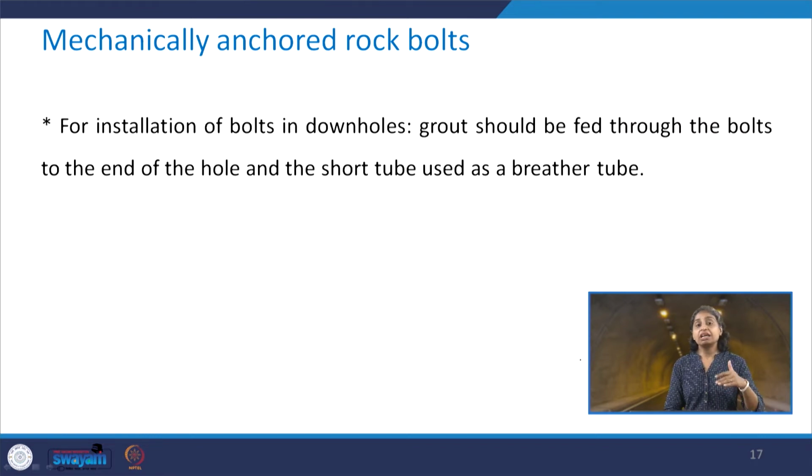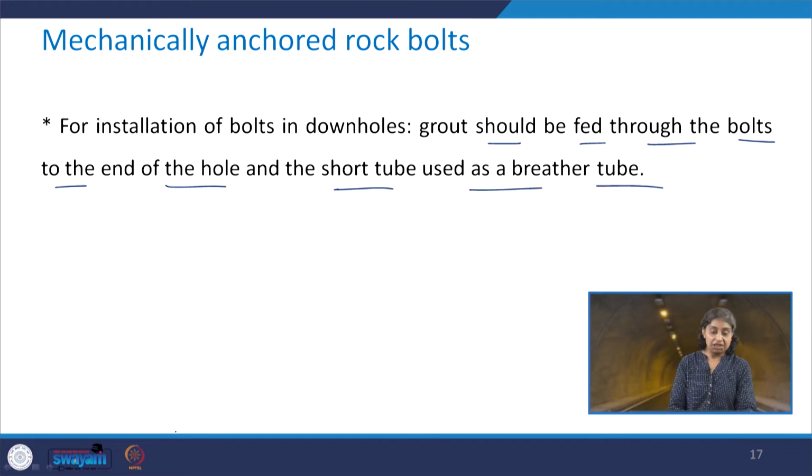Now, for the installation of bolts in down holes, so till now we were talking about up holes. If it is down holes, then the grout should be fed through the bolts to the end of the hole and the short tube should be used as a breather tube.